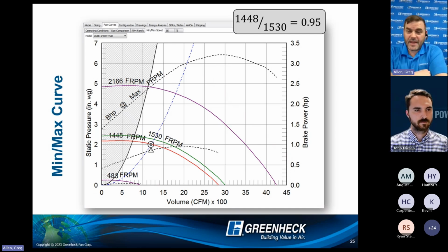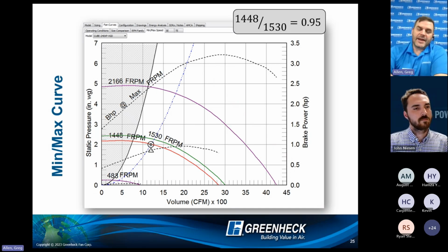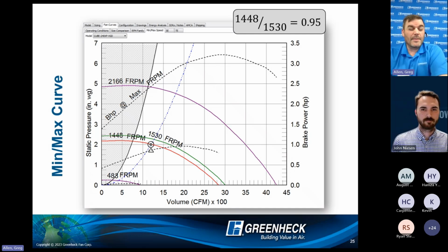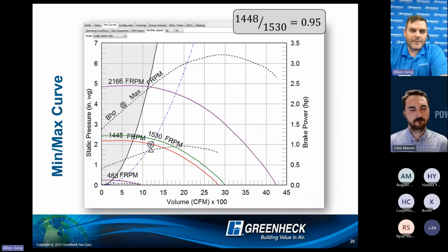But there's usually a 0 to 10 volt input. Now, when you use a modulating signal, and 0 to 10 is used for all kinds of stuff. I mean, I could be relaying information about parts per million, or position, or speed, using a modulating signal. And 0 to 10 is like the most common modulating signal in our industry. Secondary would be 4 to 20 milliamp. But 0 to 10, most EC motors can accept that. And it's a linear signal. So if I'm sending 5 volts, I'm telling the motor to go 50%, 10 volts, 100%.